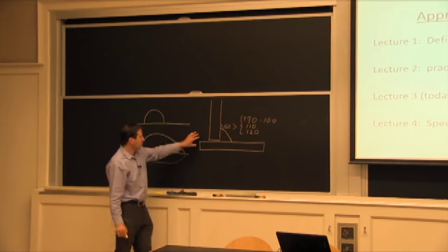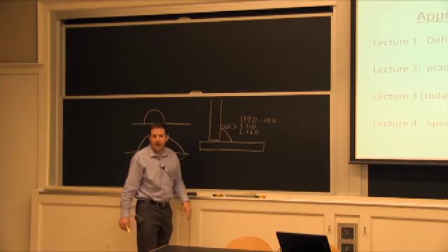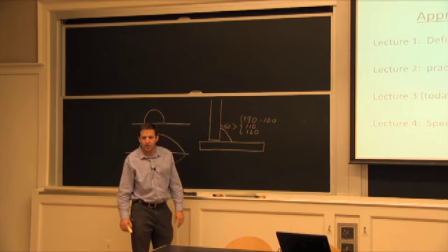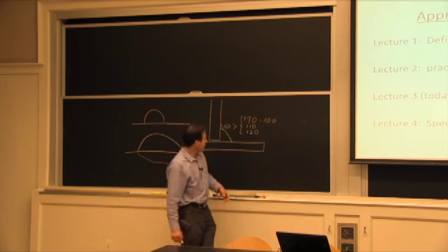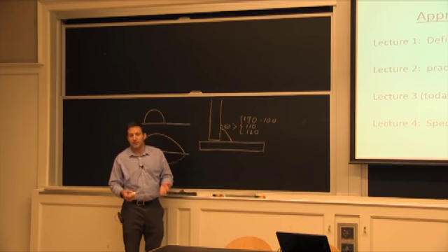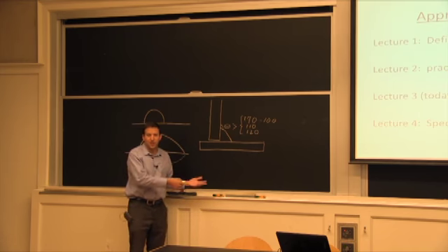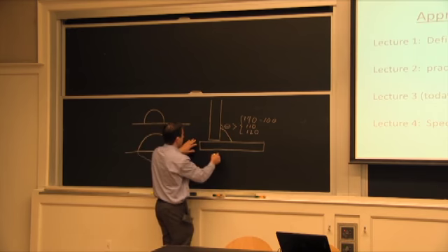So ISO is very specific about asking for a specific angle from a visual standpoint. It's still not perfect, because if I go out, most of the time this is too small to really put a measuring device. So I have to evaluate visually whether I think that it's a straight out type of weld.